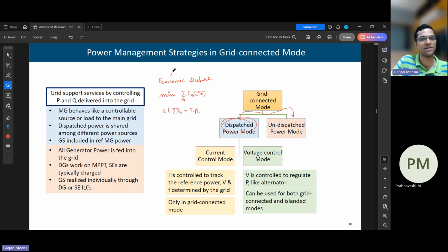And this is for thermal generators. If we solve this problem for a certain number of generators, we find out how much each generator should generate. They also have some technical constraints, that PG should be between PG min and PG max. Considering all these constraints, we can know how much each generator should generate, and it is dictated by the operational cost of these generators.